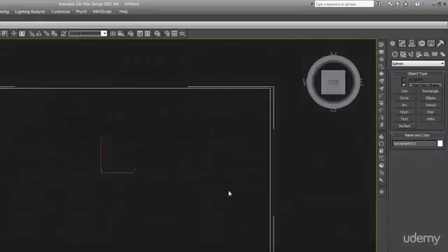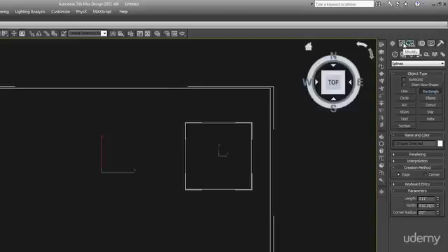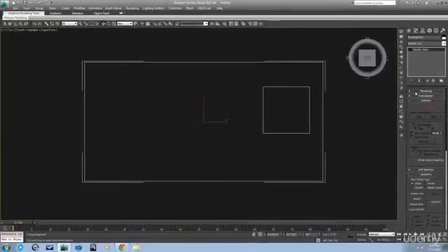Now, if you select that rectangle, then here, this is an important button. Start New Shape is checked. We actually want to add to this shape, so let's uncheck that. Then if we draw another rectangle, you can see it's all still selected because it's all the same shape. Now let's just go into modify this rectangle, and again you have